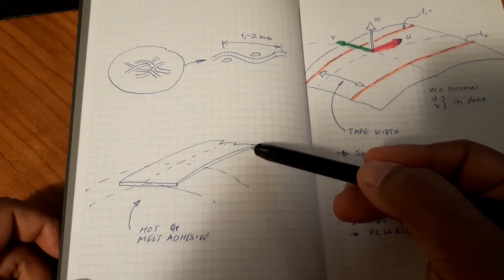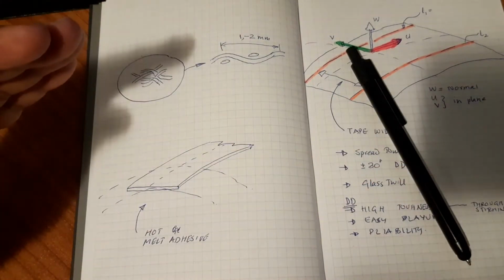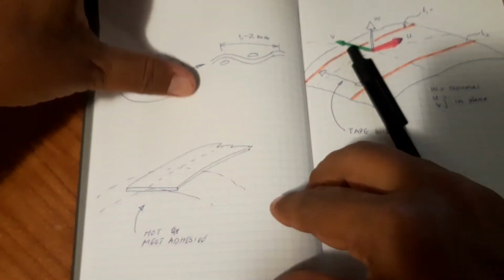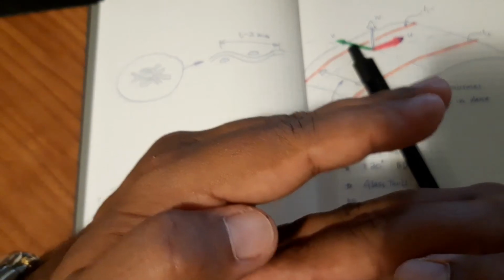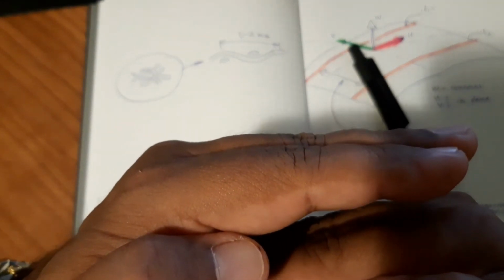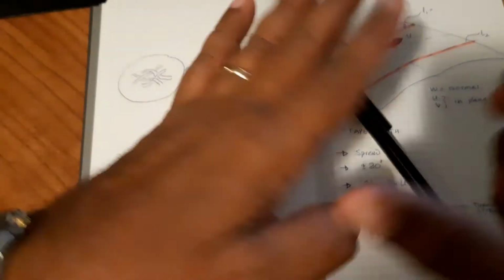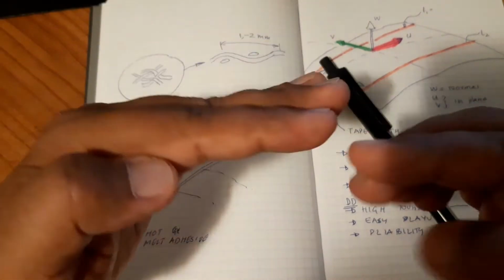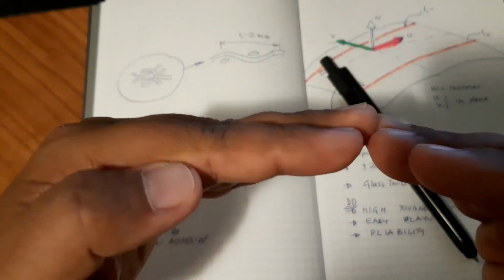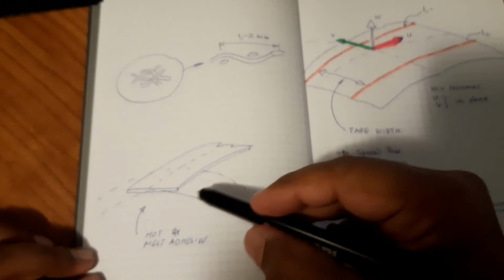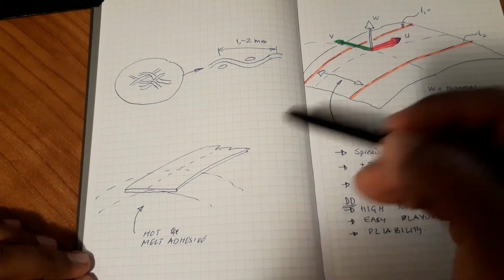So there will be kinks, because if you have any tape and you try to put it on a curvature in which this length has to reduce, and this length is longer, and you force it, this excess material, which is because of the longer length, will eventually crimp down on this surface in a very random manner, and there's no control over this.